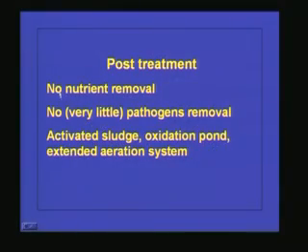So if you want to use it as a treatment unit, and if you want to meet the effluent discharge standards, whenever we go for an anaerobic treatment system, we should have post treatment. So that is what I have given here. No nutrient removal is taking place in an anaerobic system. And very little pathogen removal is taking place.